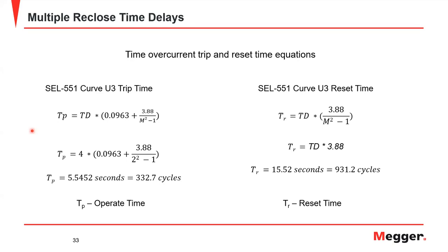Now, electromechanical relays have a feature, which is that they trip on one curve and they return or drop out on another. And that is something that can make it a little bit challenging to coordinate. So it's better to use, with the ability that we have today, a computer program to do the coordination rather than relying on hard and fast rules of use this many cycles and things like that.